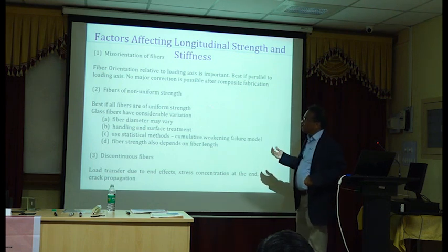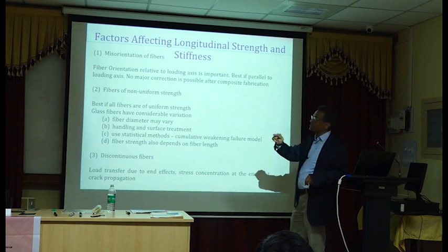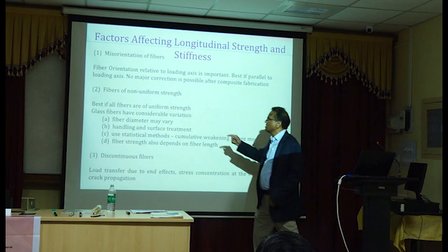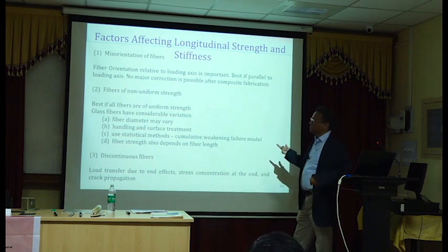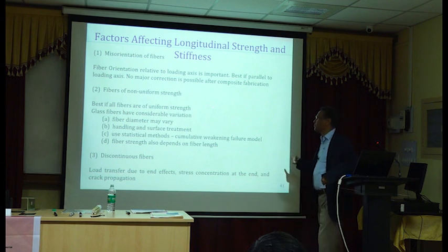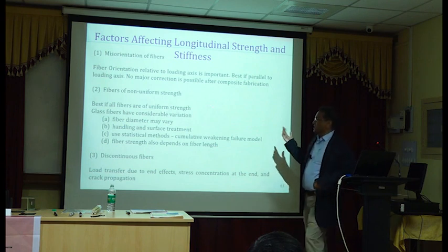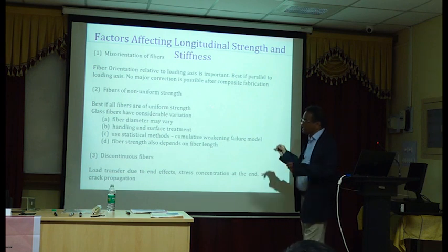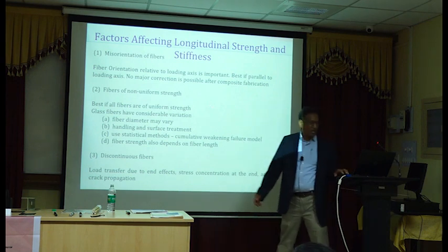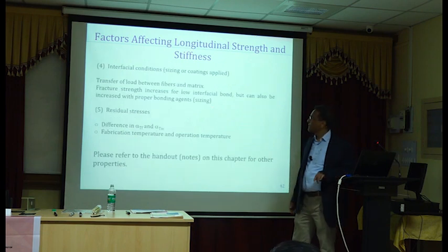And fibers can be of non-uniform strength, the diameters can vary. You saw in this picture there, micrograph, you see a lot of variation in diameter, and there can be other problems. You can use statistical methods. Fiber strength is also dependent on fiber length. So many different considerations. We're not going to go through all of these.